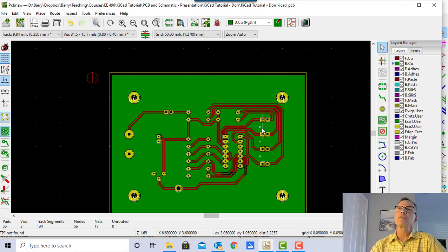And if you got a professionally made board, you would have ground right here. If you get one of our SDSU boards, what you need to do is take a little piece of wire. I usually use the end of a resistor lead and just stick it through that hole and solder it on both sides. Because again, your holes are not plated through. So that's what you want to do with an SDSU board.